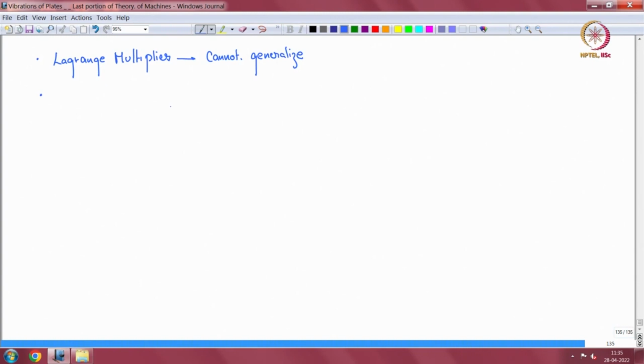That is Lagrange multiplier. Now, in general for Rayleigh-Ritz method, you need to have two terms for a single mode, the rule of thumb for each mode. Then if you have a constraint, each constraint requires one term, each additional constraint.